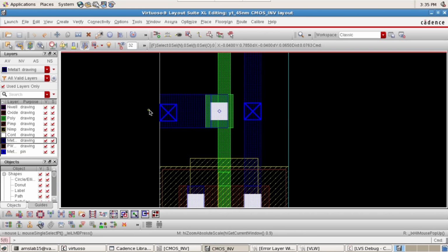And here we have to make some connections, like we have NAND plus inverter is equal to AND. So when we are making the AND connection, we have to connect this input with some other connection. Then we will not have this area concern. So in that case, what you must do is copy this layout to another file and remove this metal and merge this metal pin with this contact, so that we can make a direct contact from this output of NAND to this or any kind of instance.